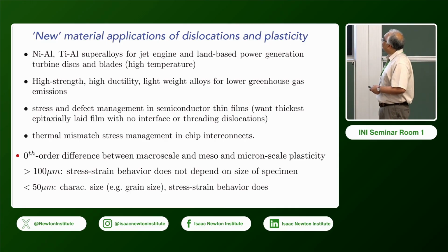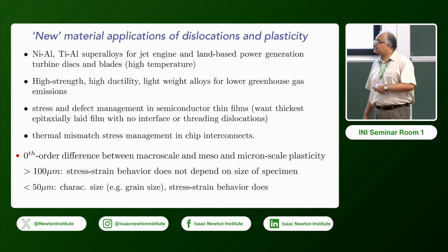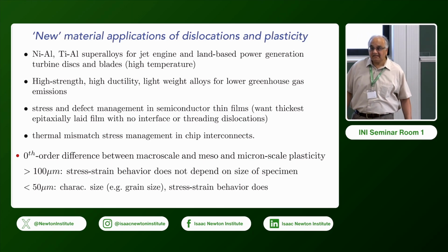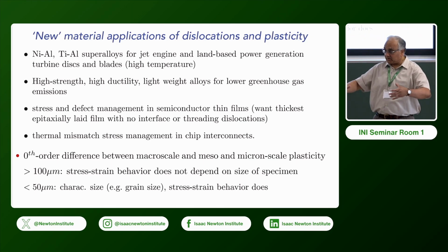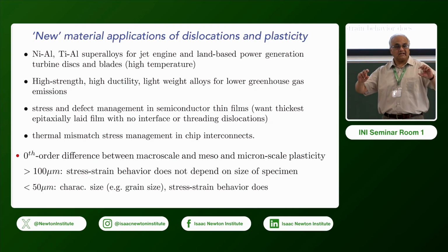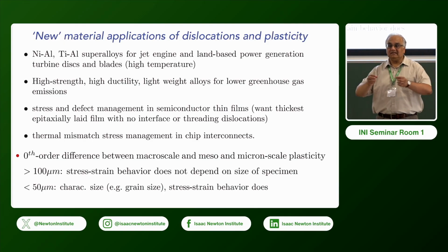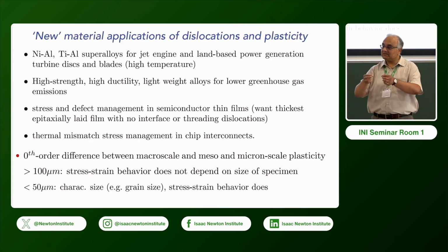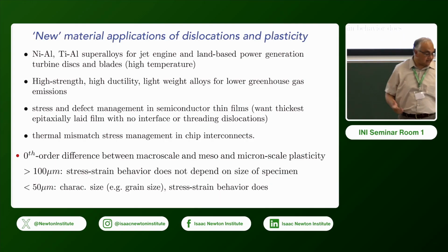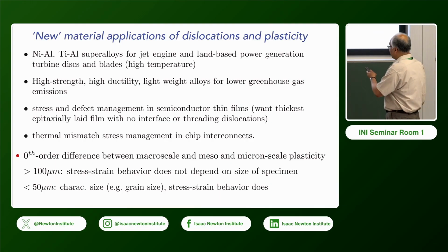Okay, so then other applications are stress and defect management in semiconductor thin films. So you want to put down a semiconductor film on a substrate. You don't get semiconductors in bulk form, so you do epitaxy. This thing grows in a state of self-strain, and you want to grow the film as thick as possible, but you don't want any defects on the interfaces or threading dislocations. So that's another area where this comes up.